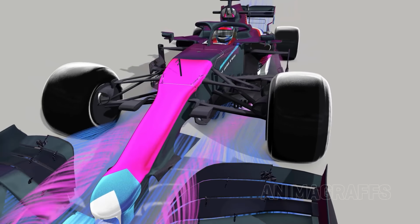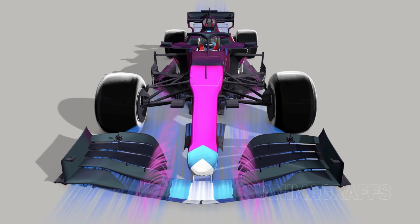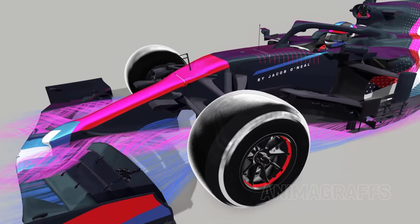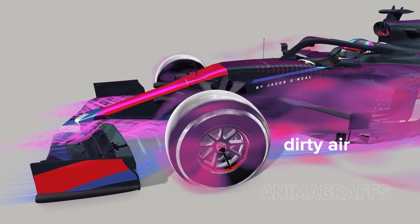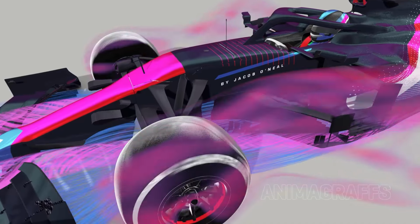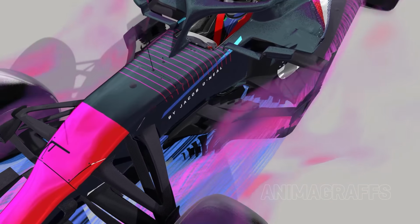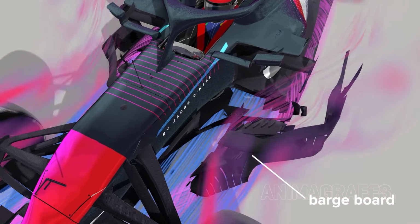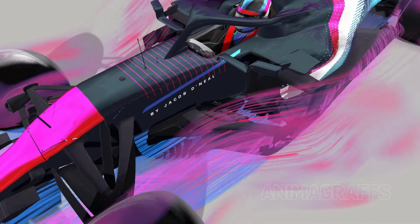So, while vortices do cause drag, they're also a useful tool to separate and seal in different areas of airflow. As a matter of tradition, F1 cars don't have fenders, and the open, spinning wheel and tire combination is a major source of dirty, turbulent air. Turbulent air is unpredictable and not very useful for aerodynamic goals, like generating downforce. Directly behind the tires, the barge boards condition or clean up some of this airflow while also pushing lots of dirty air away from the body.